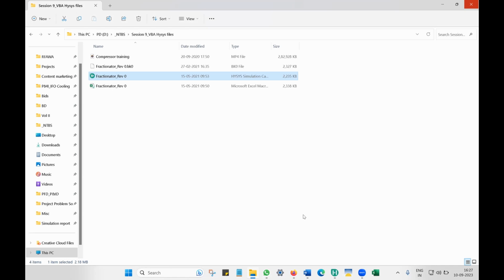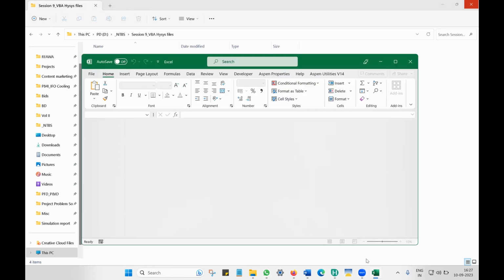In the next session, we are going to continue with our process dossier. We'll prepare cause and effect, operating control philosophy, line list, equipment list. We'll learn how to do the HAZOP. Although it is not our deliverable, we should know how the HAZOP chairman conducts HAZOP, so that during the HAZOP session we'll be well prepared, and we'll have minimum or no recommendations from the HAZOP chairman.